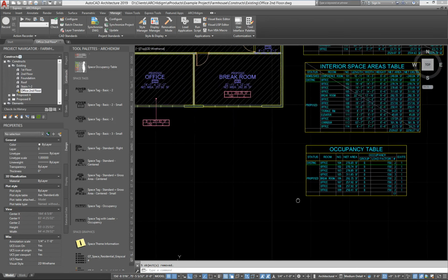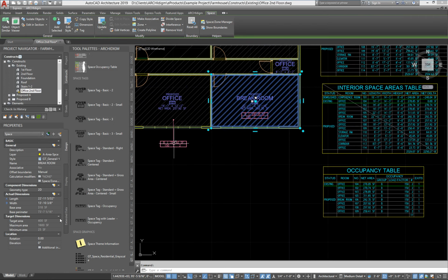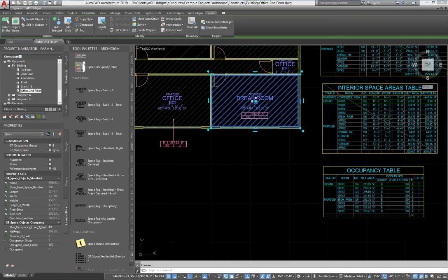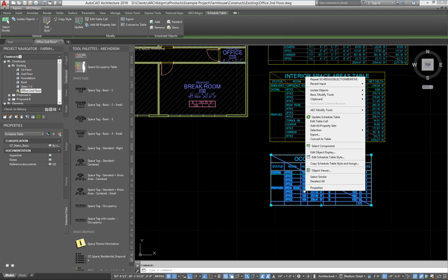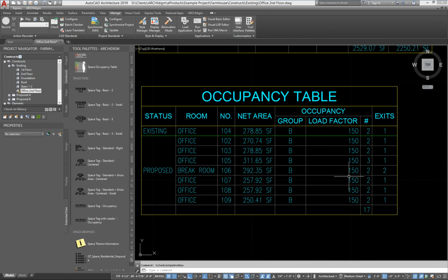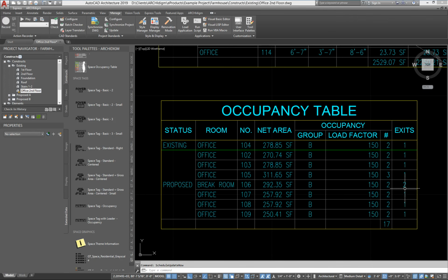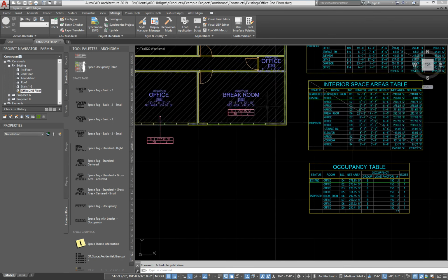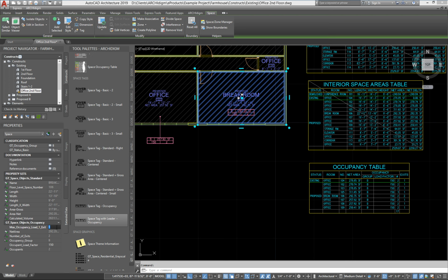Now, let's say this office here, and you were to change on the extended data the maximum occupancy load for one exit, and you were to go low enough, it will change the value over there. So suppose I went all the way down to like 1. Notice this will pop up now as a 2, right there, because it's so low now that you'll need 2 exits. One exit for each occupant is basically what's happening there. But just to show you that it works, I'm going to put that back to 49.